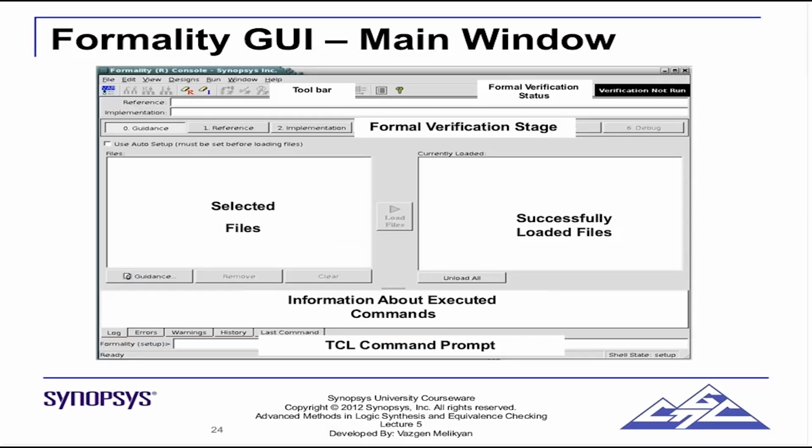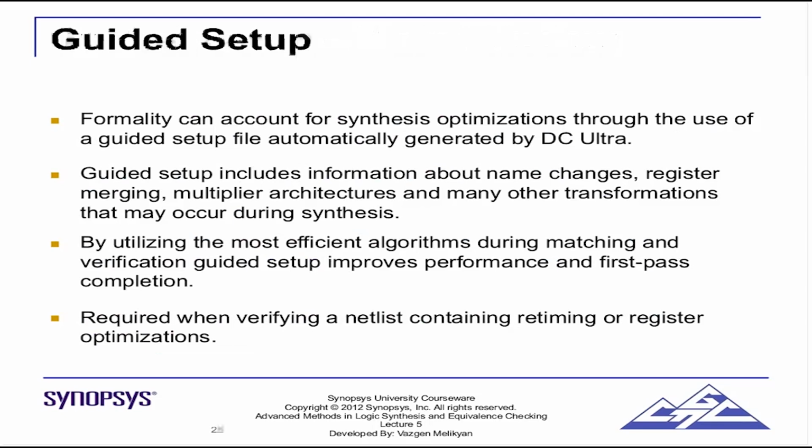So this is the formality window. A formality window is a tab-based interface. For example, there are tabs for reference, implementation, then there is debug, then there is verify, and so on. And it again supports a Tcl command interface, which is same as what is supported by Design Compiler and PrimeTime. So guided setup is a very interesting feature which is very useful if you are working with Compile Ultra. Usually it is not needed with Compile because Compile doesn't do that many aggressive optimizations.